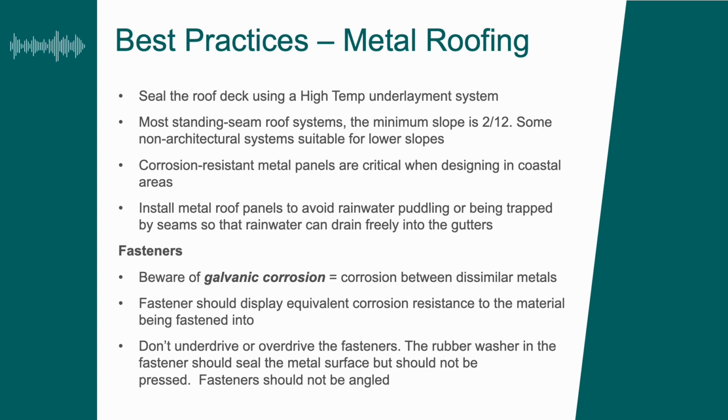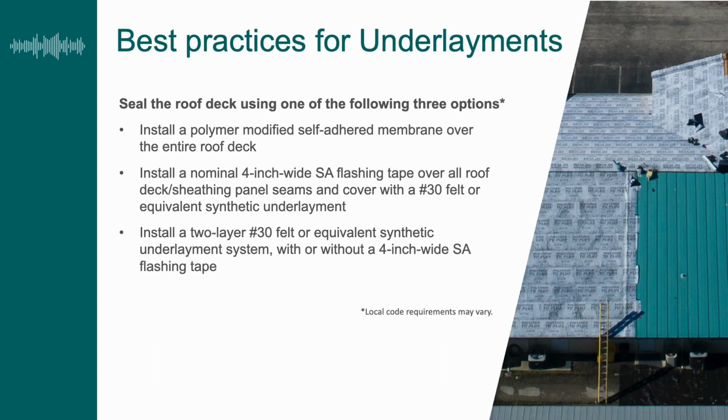So we just covered best practices for different roof coverings. And in this section we'll talk about underlayment specifically. Now, this varies a lot according to regional considerations and local code requirements, but these best practices for underlayments are for actually sealing the roof deck specifically. When you seal the roof deck, it's proven to reduce significantly the amount of damage that can be caused in the event where your roof covering is damaged or blown off completely.